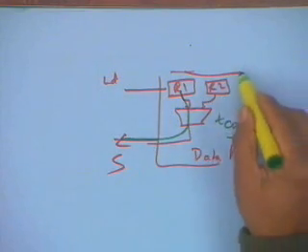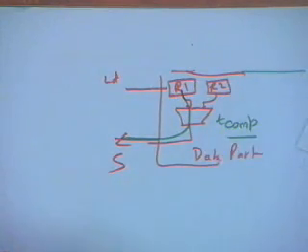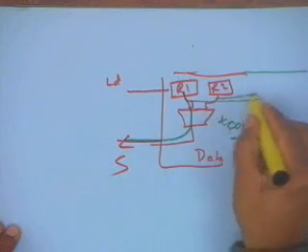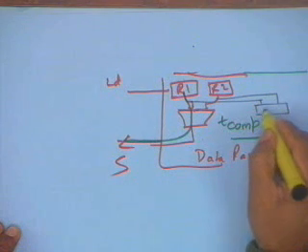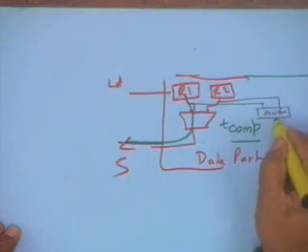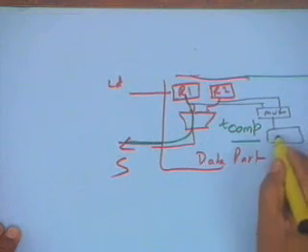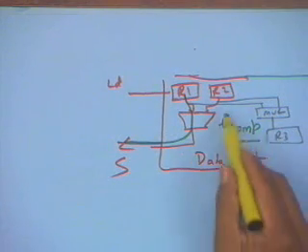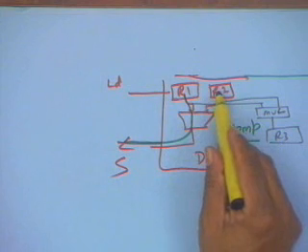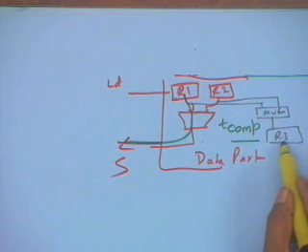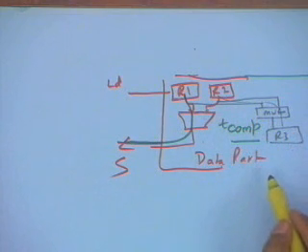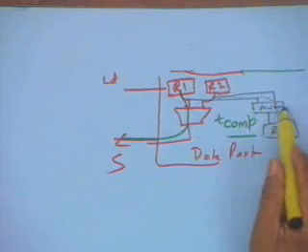Now as far as the TDP is concerned, I could have these two register outputs going to a multiplier and going to another register. This also has a load enable. So within a clock period, after I have given the load, and I can give the load enable for this in the next clock, within that this output should be stable. So this may be determining my TDP.